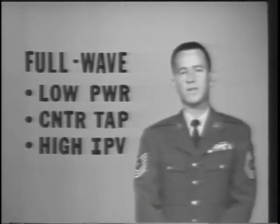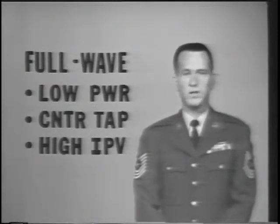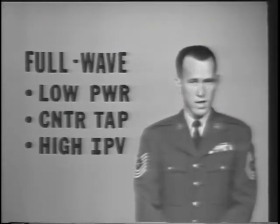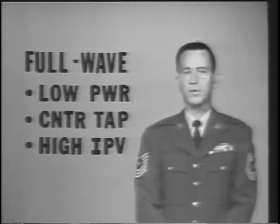Another limitation of the full-wave rectifier is the peak inverse voltage applied to each non-conducting diode. It is double the output voltage. Now this means that rugged diodes and rather large transformers are needed to supply high output voltages. There is a definite need then for a rectifier without these limitations. The bridge rectifier meets this need.